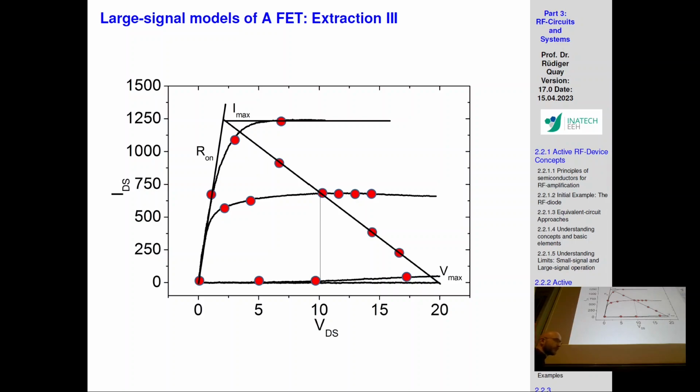Increasing from lower gate source voltage to more gate source voltage, my curve should just go like that. But obviously, your current curve doesn't just go like this, it has a bit of an inclined S shape, and that inclined S shape is the non-linearities that occur when you either have a low driving power, low gate source voltage, or when you have a high gate source voltage or a high driving power. Why is the driving power affecting it? Because remember, we're driving a sinusoidal signal with a certain voltage swing. The more this voltage swing increases, the more it pulls your gate to a higher voltage.